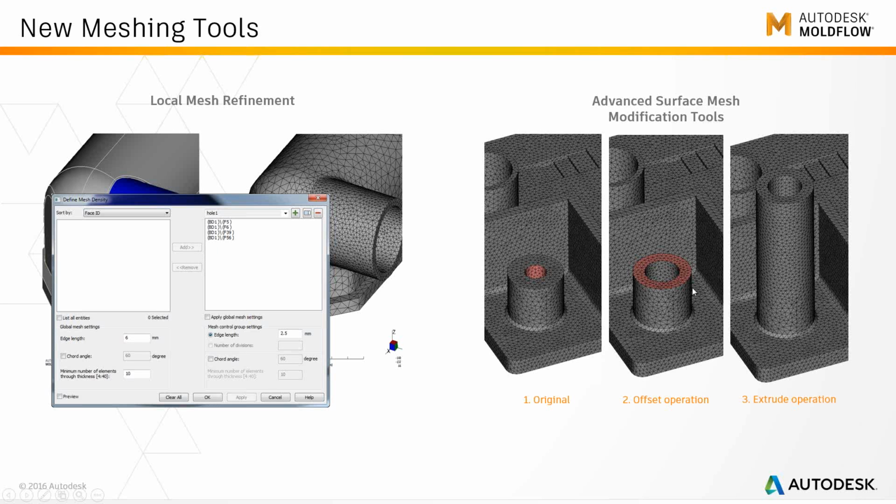And we actually also have created some new tools that basically allow us to directly manipulate the surface mesh. For those of you that have used the Scanim technology preview, this was available, I think, in the last technology preview already. But we can now make non-planar selections. Let's say I can select with 2 mouse clicks the interior surface of this boss, and I can say move this in a negative direction by 1 millimeter, which gets me this. And then I selected the top surface of this boss, and I say extrude this top surface by 10 millimeters.